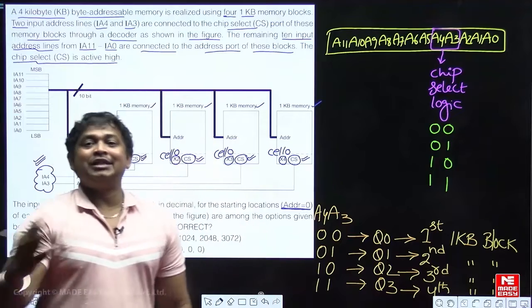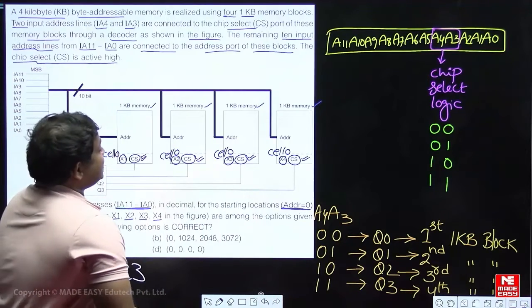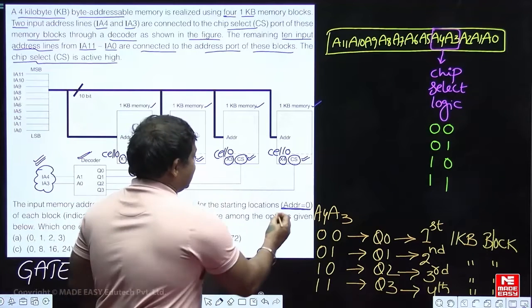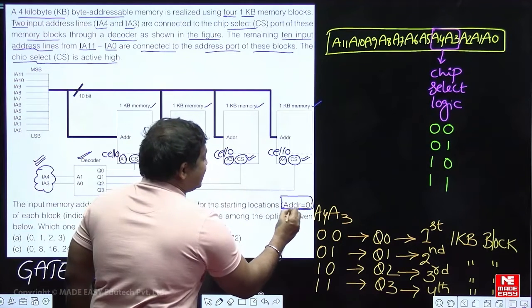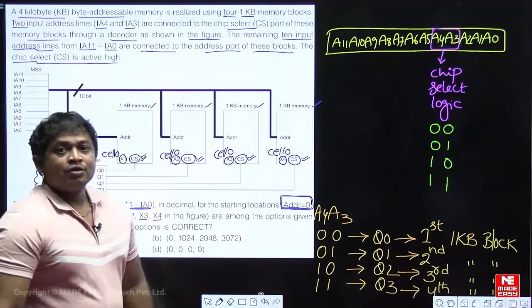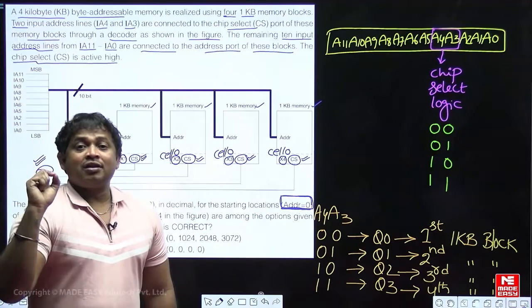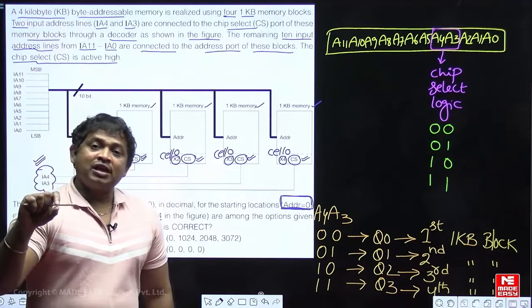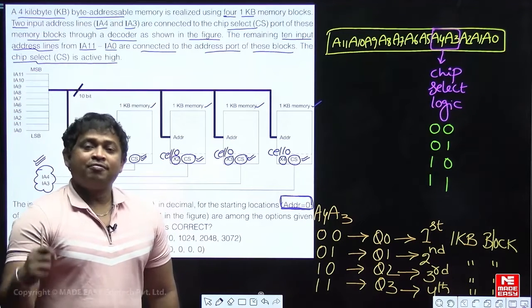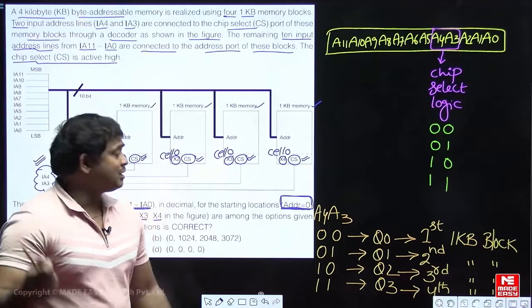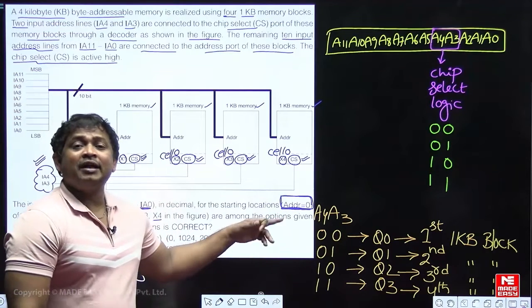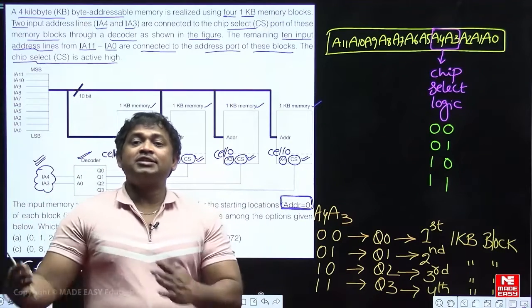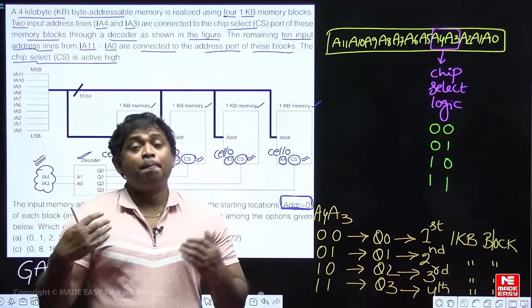Address 0 means cell 0. Okay. So cell 0 address is nothing but all zeros. They mentioned clearly address equal to 0. So starting address should be all zeros. So we need to activate the first cell from the first bank or else first block, first cell from the second block. First cell in the sense starting cell is nothing but address 0. So I want the cell 0 accessibility from each bank or from each block.